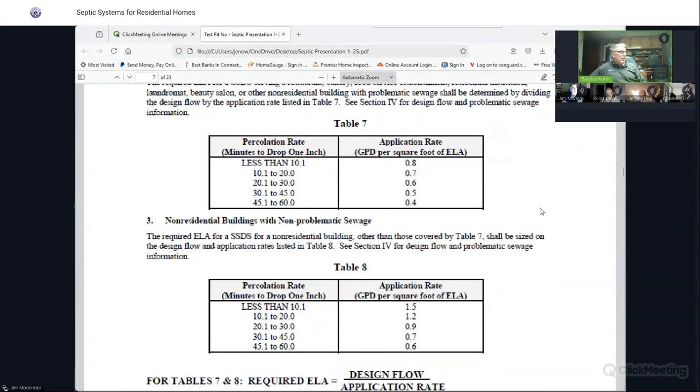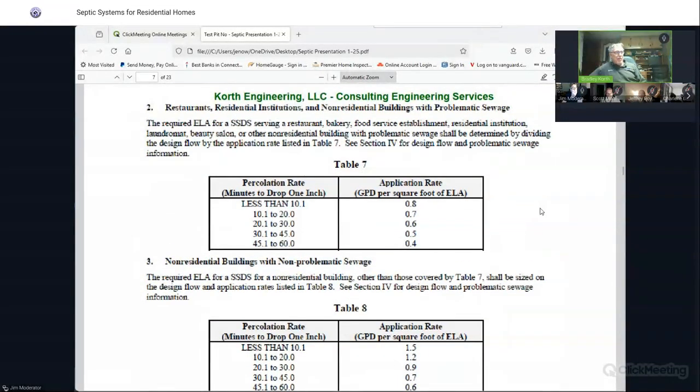And may I ask a question or bring up a point? Yeah. My name is Marlo, and I've noticed over the years when we're doing residential inspections, and it's just an observation of mine, that in a development where you're bringing in city water but dumping it into septics, quite often I'll see a lot more failures in those areas because we're bringing water into the site, but we're not piping it out.